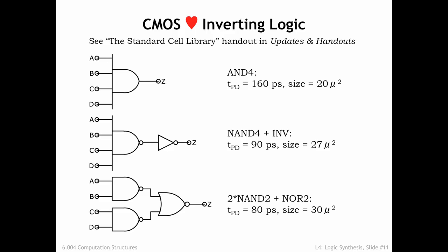How can this be? Especially since we know the AND gate implementation is the NAND inverter pair shown in the middle circuit. The answer is that the creators of the library decided to make the non-inverting gates small but slow by using MOSFETs with much smaller widths than used in the inverting logic gates, which were designed to be fast.